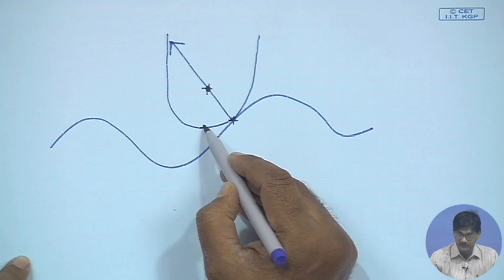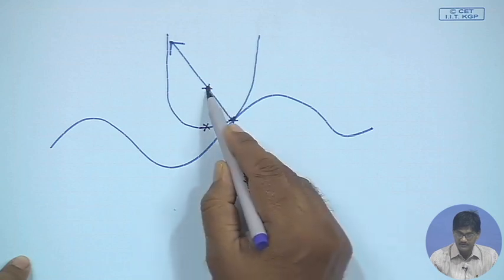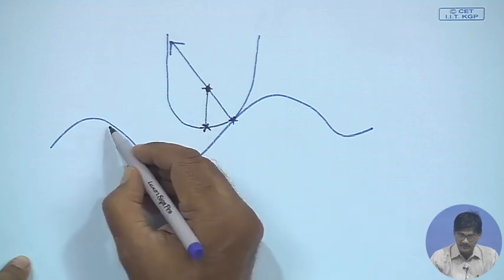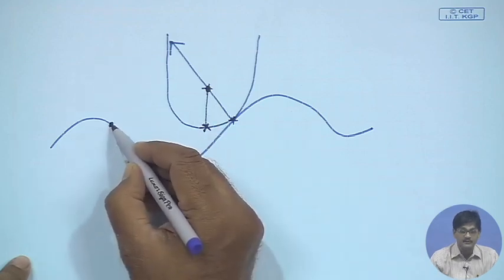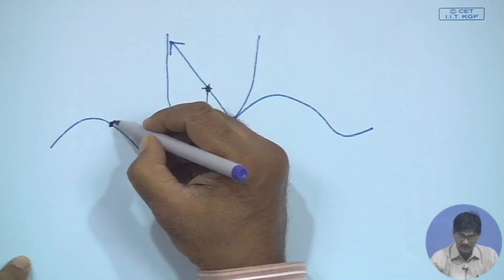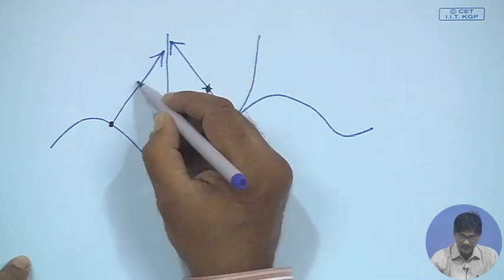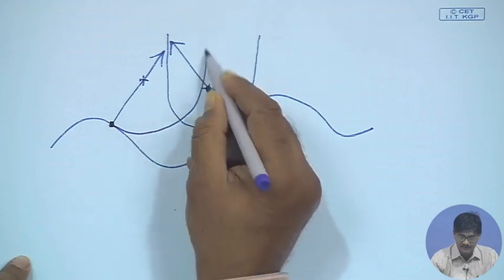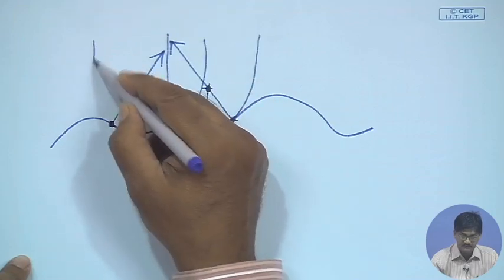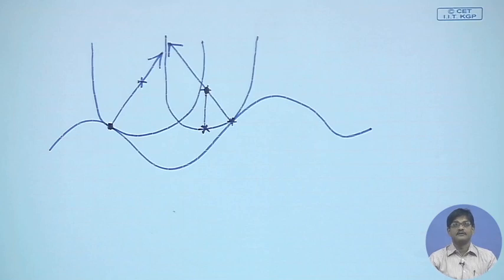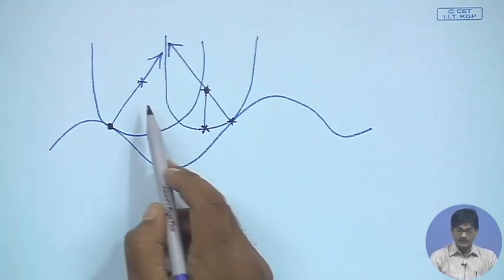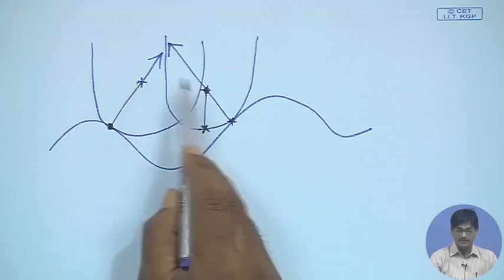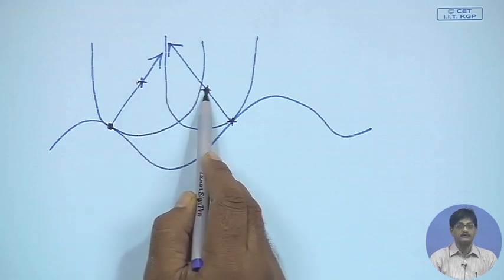I could have given this point also. This point is just a move along the z axis by radius, you will get this point. So, that way if I have this point as the cutter contact point, I can draw the normal, I can move by the radius, I can say this is the center of the spherical end of the cutter, this is the cutter position. That is it. So, I can draw the cutter uniquely once I have defined the position of some constant point on the cutter.